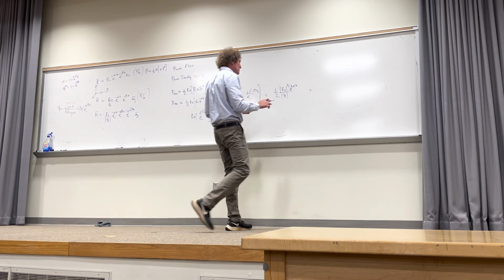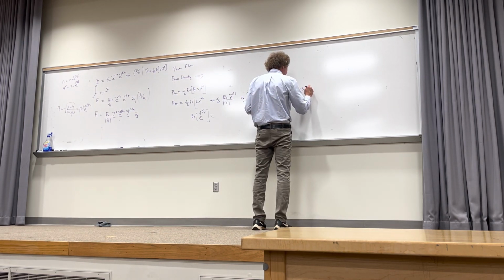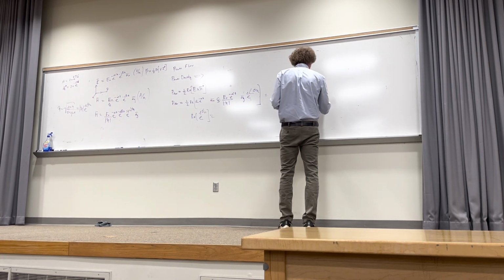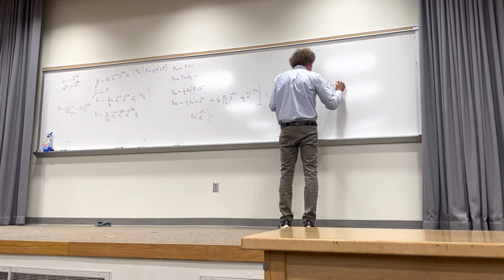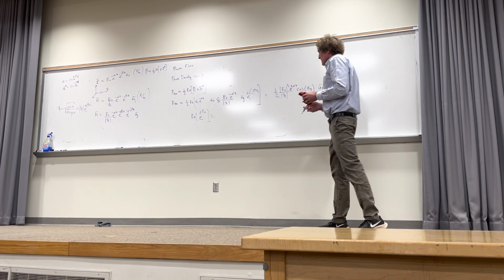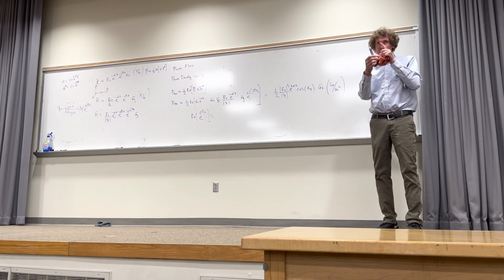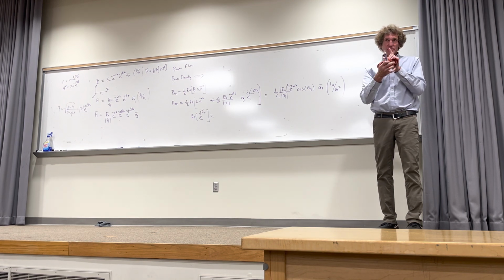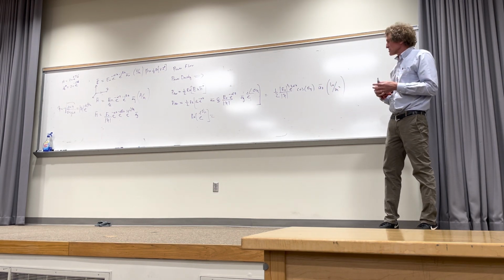So now it's going to be cosine of the angle associated with eta. And this would be in the az direction, and it would be watts per meter squared. So it's power per area that's flowing. So if you have an electromagnetic wave, if I've got an antenna, I'm propagating it at you, that means the power density coming at you would be this in watts per meter squared.